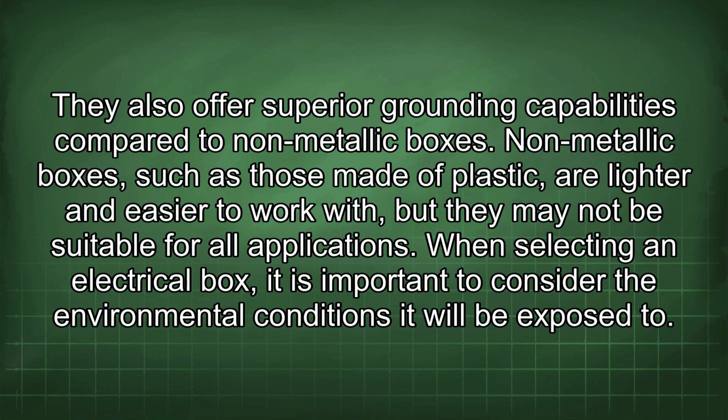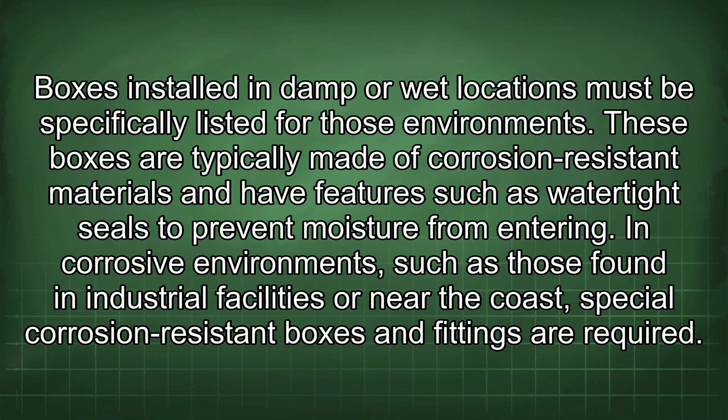suitable for all applications. When selecting an electrical box, it is important to consider the environmental conditions it will be exposed to. Boxes installed in damp or wet locations must be specifically listed for those environments. These boxes are typically made of corrosion-resistant materials and have features such as watertight seals to prevent moisture from entering.